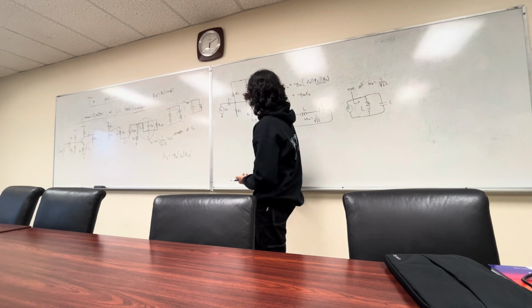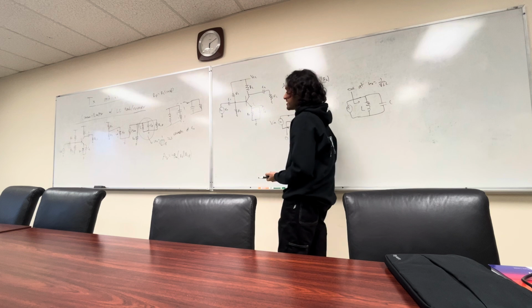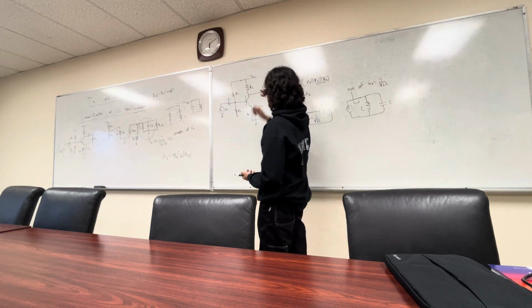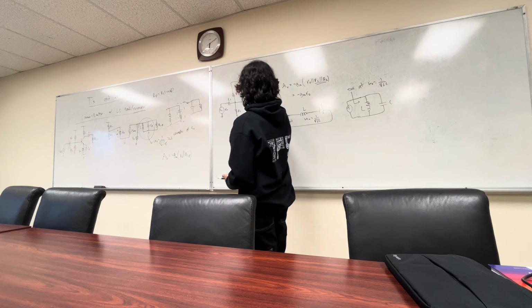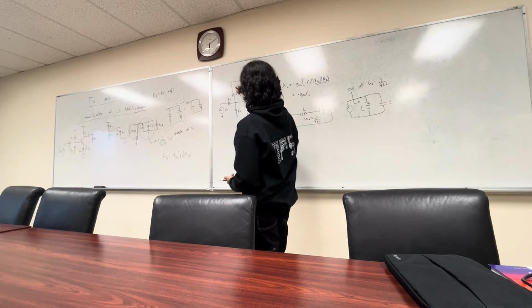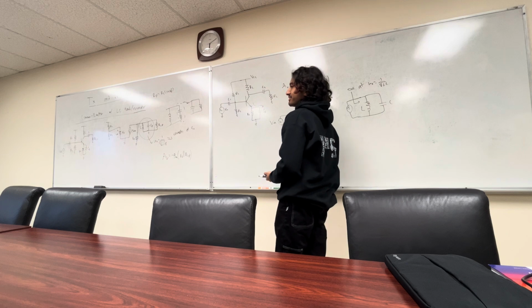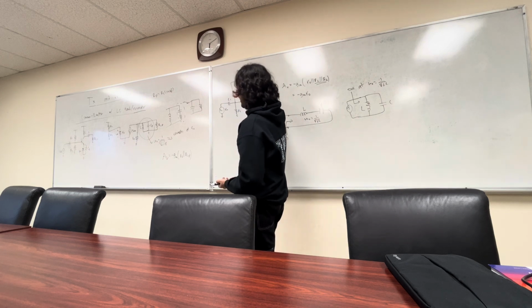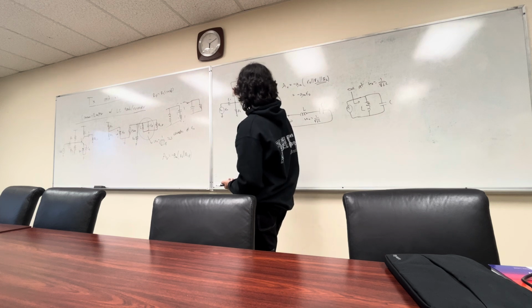Exactly, yeah. Remember that we need VCE to be at least 0.2 volts for it to be in the forward active region. And if RC is super large, say we have 1 milliamp, 1 milliamp times 1,000 ohms, it's only 1 volt. Make RC larger, and see what happens. So that's one area we can't really mess around with too much. We need good biasing, right?